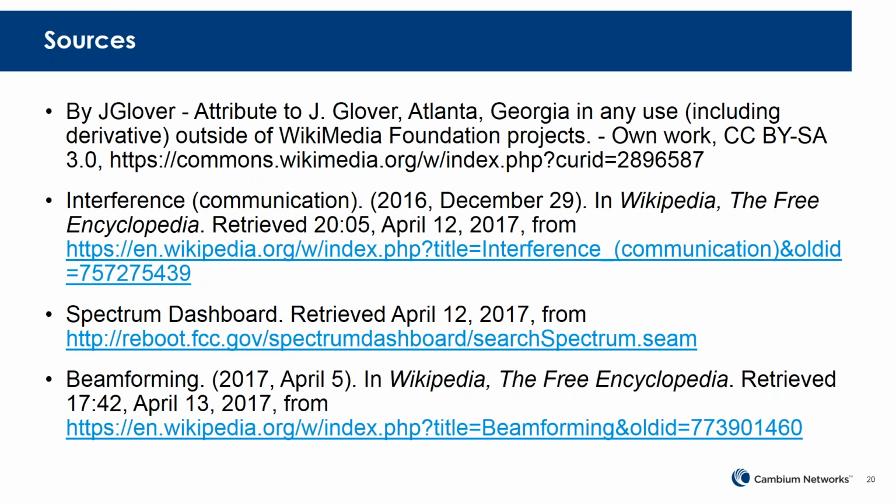Can we explain GPS sync, i.e. auto sync, free run, and generate sync on the PMP 450? Sure. We talked about GPS sync, and how critical it is that all the frames at a tower and a network are lined up so that they're transmitting at the same time and receiving at the same time.